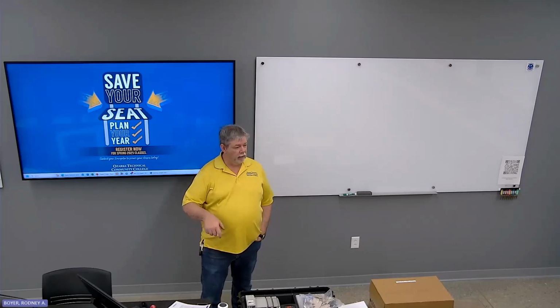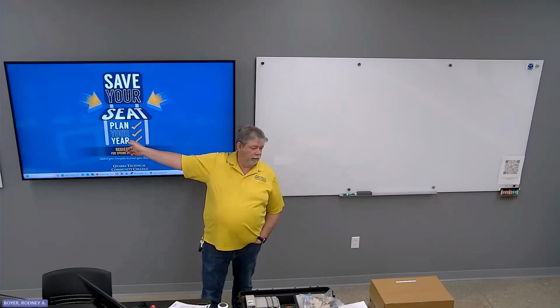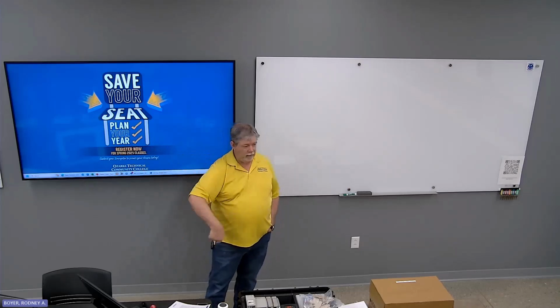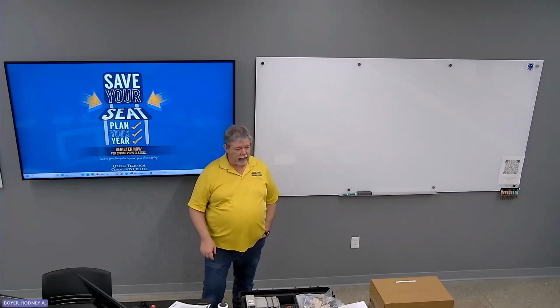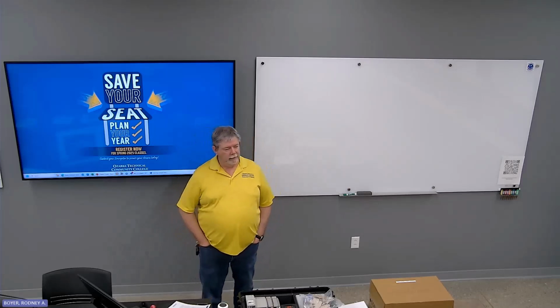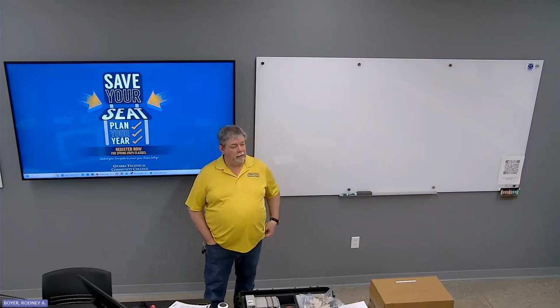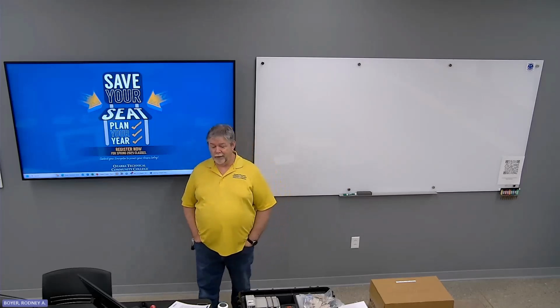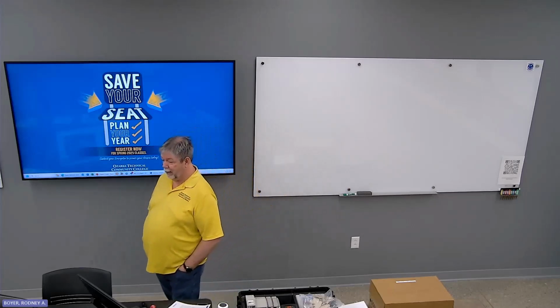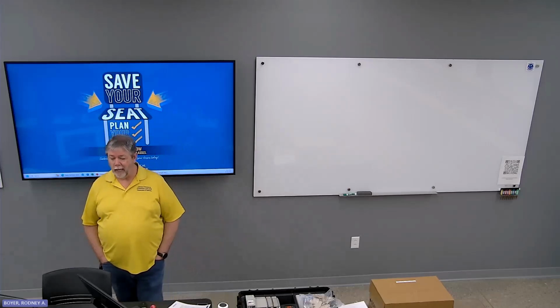You have the full cable. There's a roll former down here in the PMT area, and it's got the cable around it. So if you hit that cable at any point, it pulls the contacts open on the e-stop switch. Then it won't restart again until you go over and manually reset it. That is something else that defines what an emergency stop is: it has to be locked in position when it's actuated.